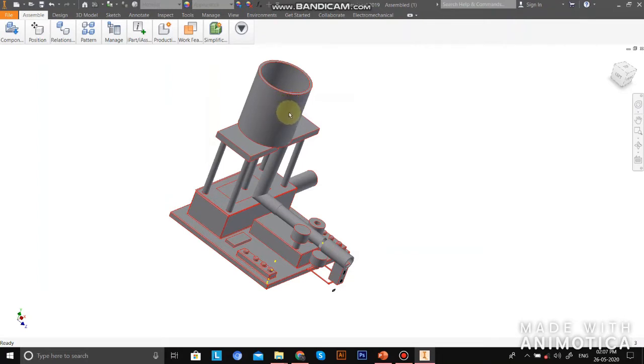Once the machine is turned on, the DC motor in the container starts and segregates the unwanted balls from the container and removes them out of the machine through the pipe joined at the side of the machine. Now the balls pass through the pipe where two adjacent DC motors give motion to the ball. Next, the servo motor changes the launching angle according to the user. If the container gets empty, the LED will give an indication. Similarly, if there are any obstacles, the sensor will sense them and indication is given through the LED.